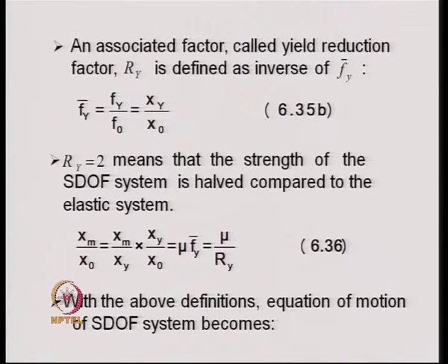In order to make the formulations and the necessary curves for understanding ductility, we introduce certain parameters into the analysis procedure. First parameter is F bar y. F bar y is a non-dimensional yield force defined by Fy divided by F0.